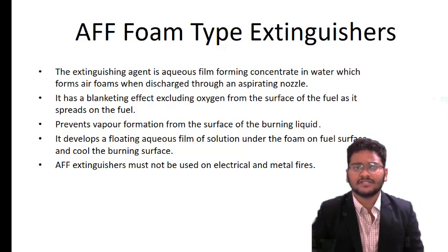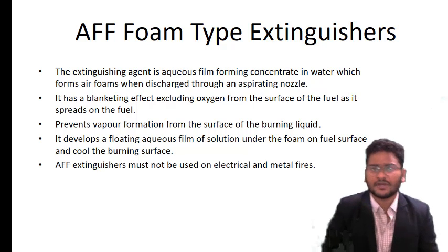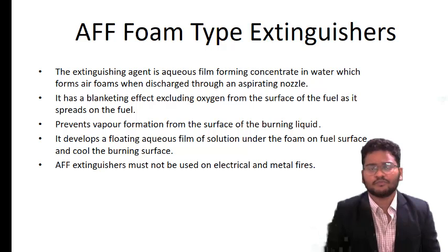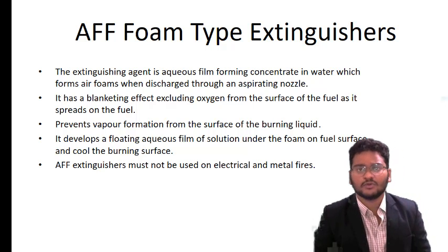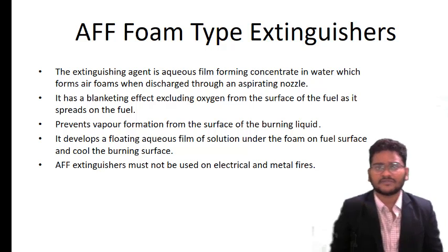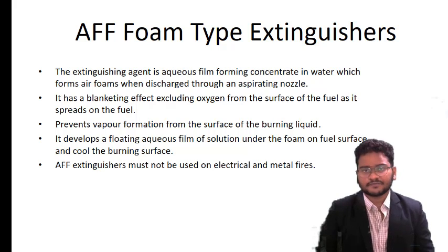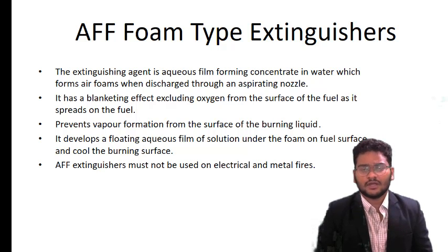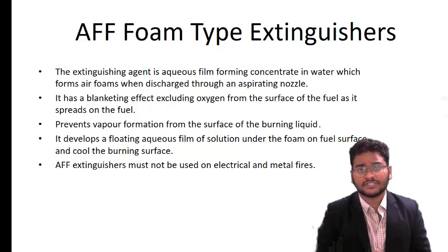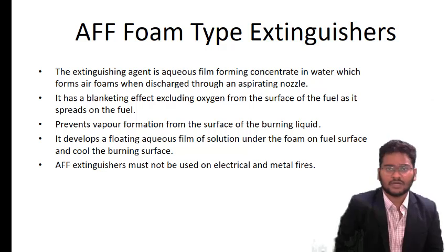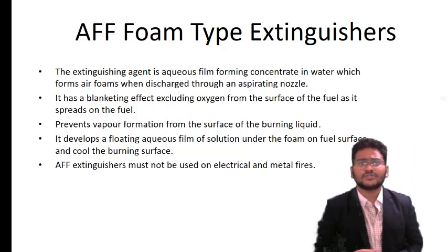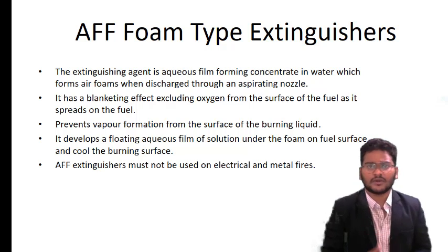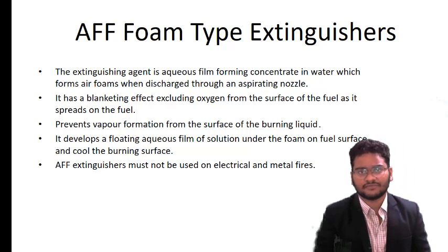What will happen is the aqueous floating foam will be distributed on the total surface area of the fuel. It will control the vapor pressure, so automatically the vapors which are rising from the fuel will be controlled. Then the contact between the fuel and the oxygen will be cut. So it leads to the control of the fire, and automatically it will extinguish the fire here.